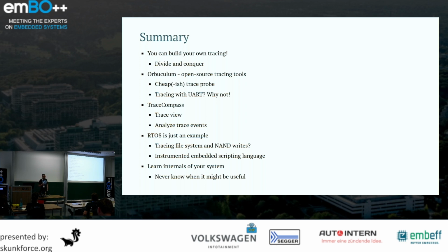And Orbuculum also gives you tools to work with trace data, not only capture the data. You can use TraceCompass to build whatever visualizations you want and analyze the trace events. And tracing RTOS is not the only thing that we can trace. You can trace file system and how many writes to NAND device are happening and how long they take.